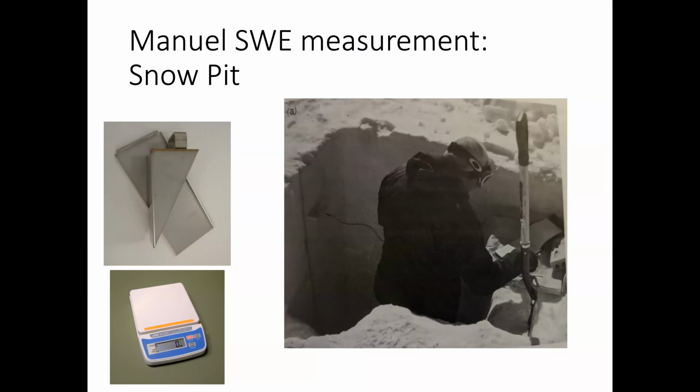The Mount Rose sampler is a quick, easy way to estimate snow water equivalent, or SWE, but snow pits are another common way that generally give more precise estimates. However, they are very labor intensive, especially if the snowpack is deep. After a pit is dug, the device called a rip cutter or a Kelly cutter is used to sample the snow, shown on the upper left here. Like the Mount Rose sampler, the snow is then weighed to estimate the SWE.